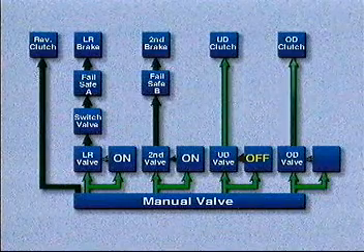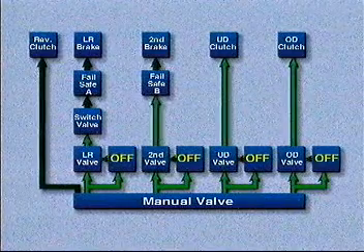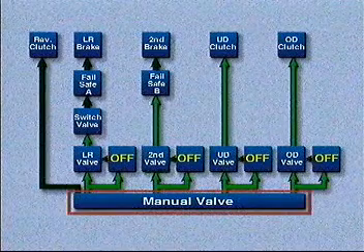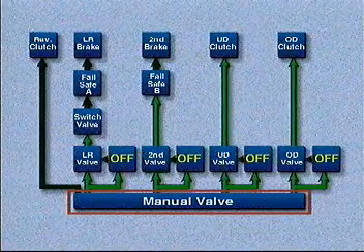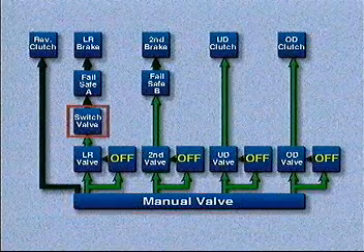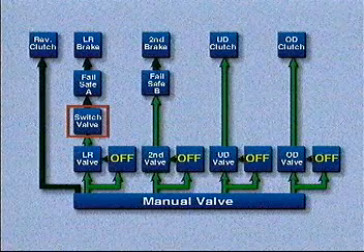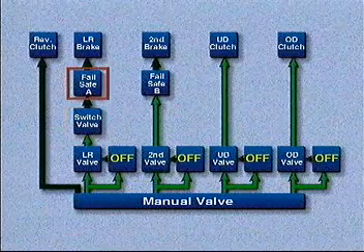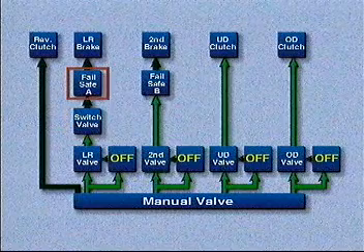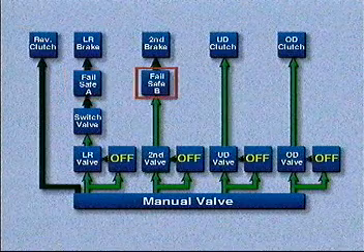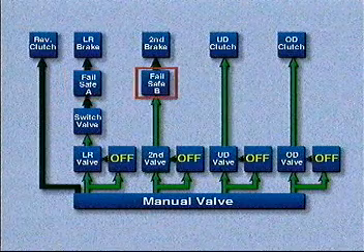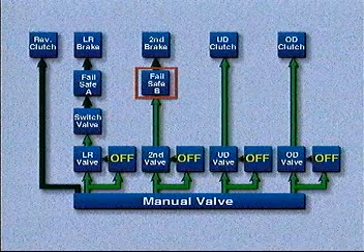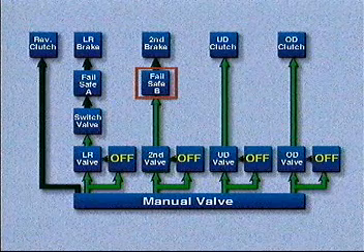In failsafe, when all solenoid valves are off, the manual valve controlled by the shift selector applies pressure to the overdrive and underdrive clutches. A hydraulic switch valve prevents line pressure from reaching the low reverse brake. The valve moves according to pressure from 2 hydraulic circuits. Failsafe valve A releases any existing line pressure on the low reverse brake. Failsafe valve B prevents line pressure from reaching the second brake and releases any existing pressure. Failsafe valve B moves according to pressure from 4 hydraulic circuits.